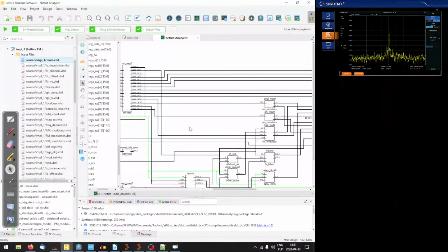And then we take that signal and we have to shift it right by, let's say, 4 bits to make the amplitude a little bit smaller, and then add it to the signal that we read from register 9. Yeah, this one. And after that, it should work, and we should be able to test it.